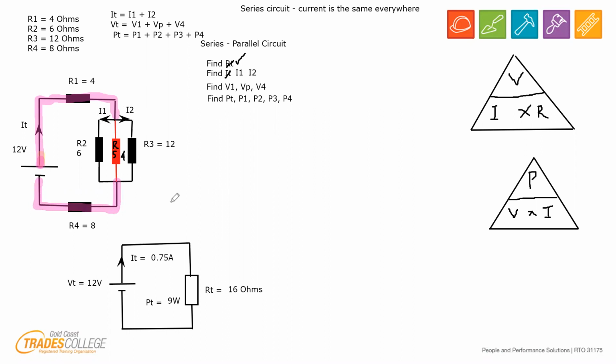Now then, this is a really, really important point. You will remember, and I've left it in for this reason, that when we simplified the parallel circuit, we had an R5, which was a combination of the two. R5 was 4 ohms. Well, if I didn't have this parallel circuit, the current would have kept going. And this current, which I've just drawn in here, I'll do a circle around it. This bit here, guys, is what we need to work out VP.